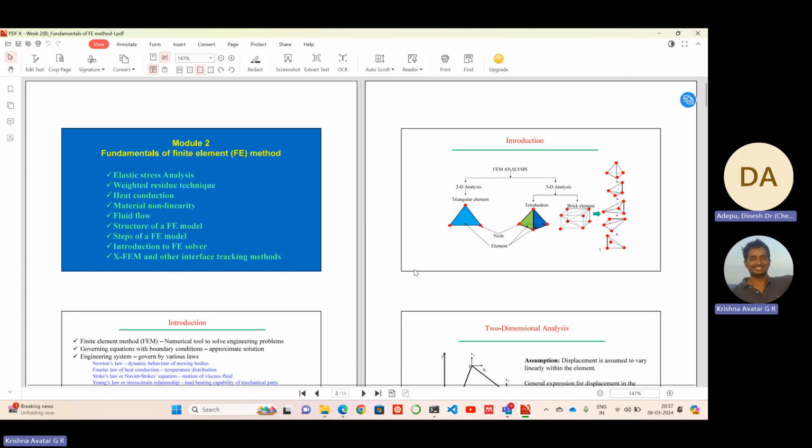You might have shear locking, so to eliminate that, they use different kinds of function extrapolation. You extrapolate at some point, create a mesh, and then do it in the middle. It might give you a different value, a different approximation. That is how it is dealt with actually.